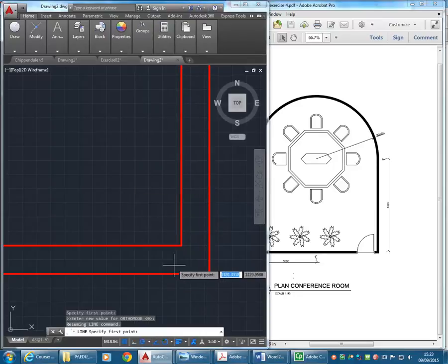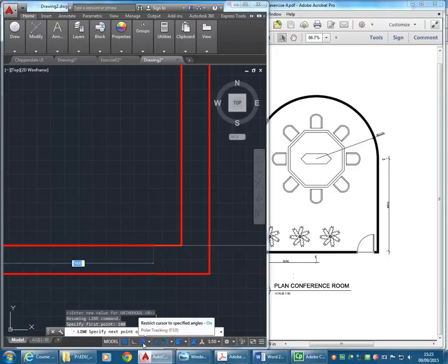But another maybe slightly trickier way but less clicking is to just hover and move to the left from that point, type in 100, and it should snap that way with object tracking. Yeah, object snap tracking, but that should be turned on anyway. Well, the button's turned off, but it's down here if it's on. Oh, so it is on. So that one there shows snapping reference lines, they call it now, but you can see in grey object snap tracking.